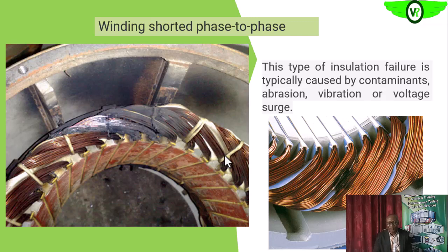One of the phases can vibrate and make contact with the other phase. Since the insulating capacity has been reduced, that can cause failure. Or it can also happen when you have vibration coming from an external fault condition, maybe a misaligned bearing or a coupling that is not properly made, increasing the vibration of the electric motor. We have soft foot on the electric motor, also increasing the vibration. All of those can contribute.